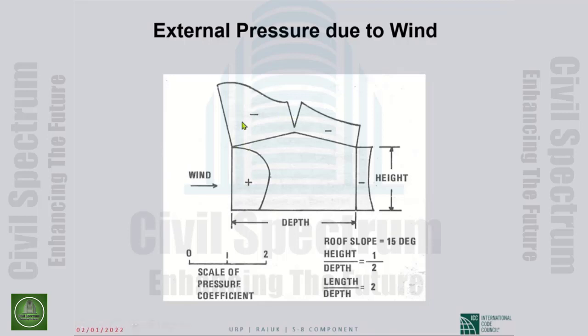And when that happens, the wall doesn't have lateral support. It comes down. This is the mode of failure that we have seen after every serious wind event. And so the basic point that I'm trying to make is that the roof has to be held down to the building, and very importantly, the building has to be held down to the foundation. That I have found missing.